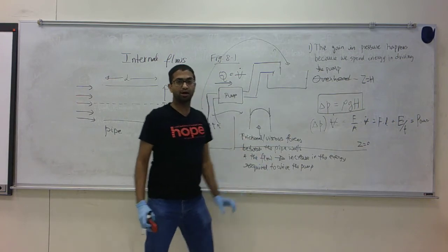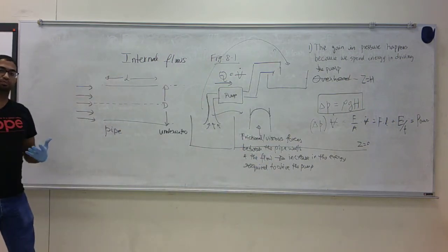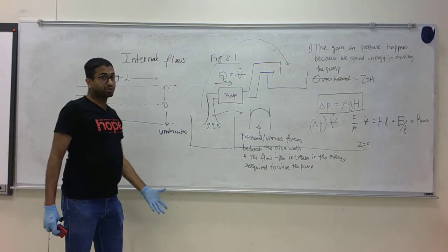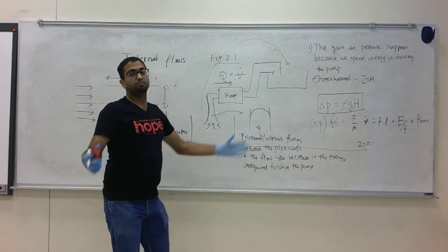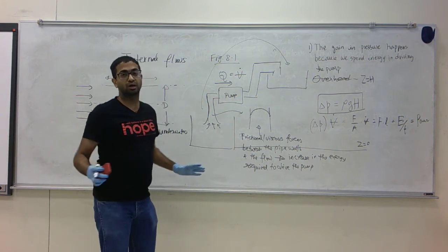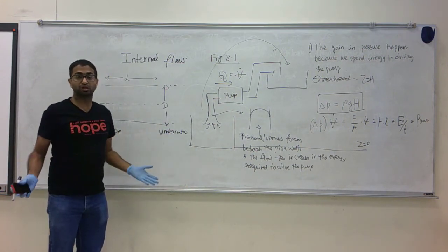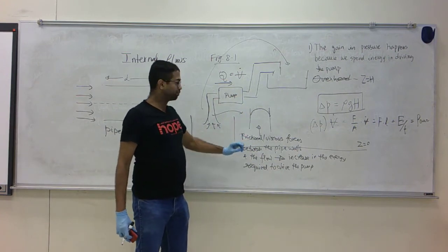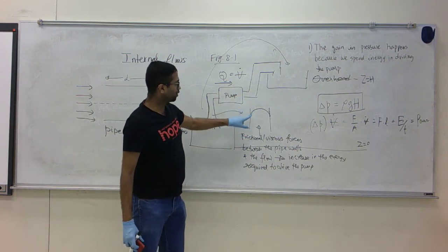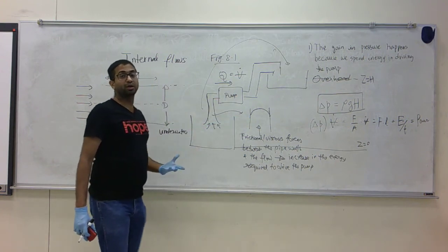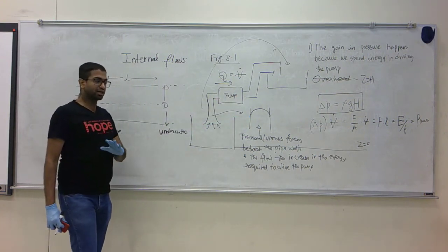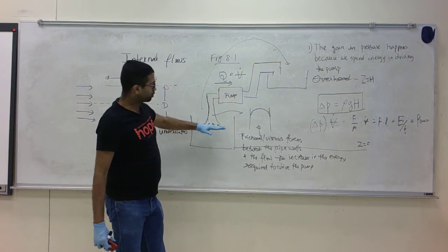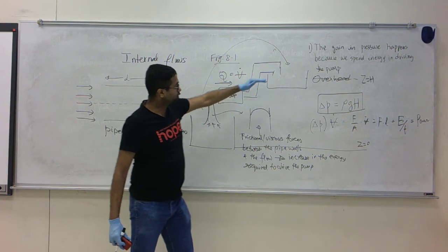That's the gain in hydrostatic pressure, or the potential energy of elevation. While you do that, if by some magic all the viscosity of water goes away, or in other words, when water flows through a tube, there are no frictional forces between the water and the walls, then what you get is the ideal case. That is, there is no extra energy required other than the energy you need to put to take the water from here to there.